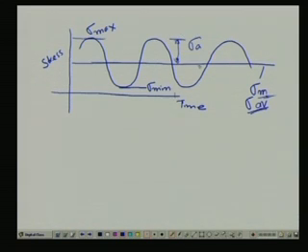From here it is a sigma mean line. Some definitions are given for the sigma mean, that is the summation of this by 2, an average, and the difference divided by 2 is the stress amplitude. We will come to these derivations and the design aspects after a short while, or maybe in one or two lectures after this.